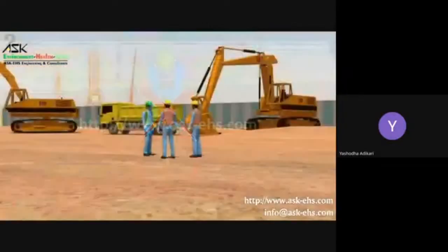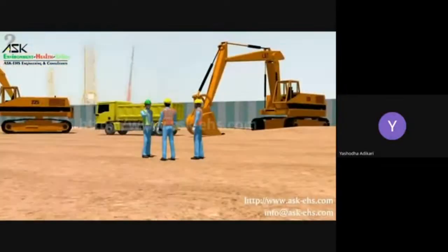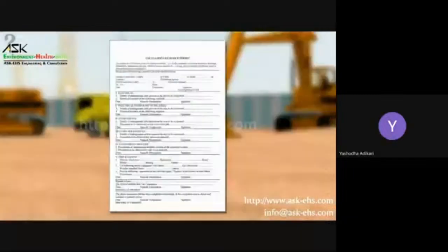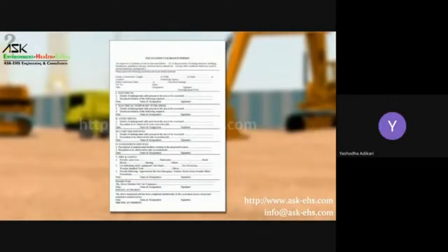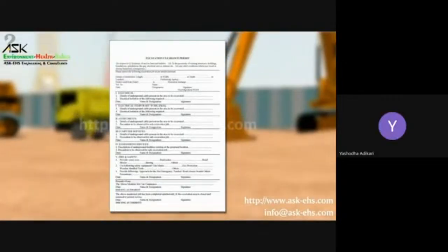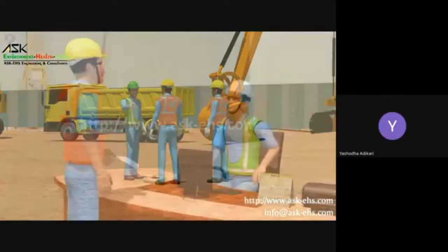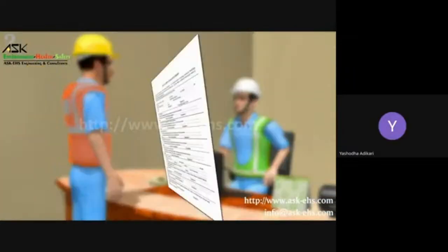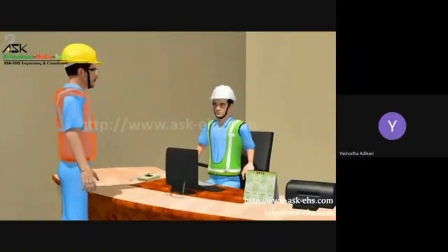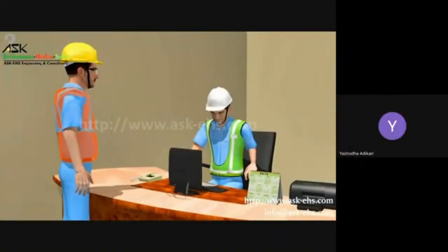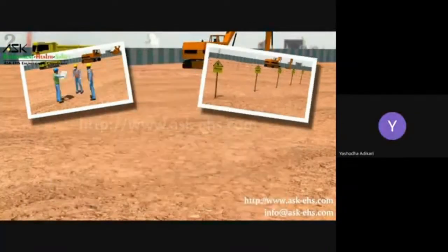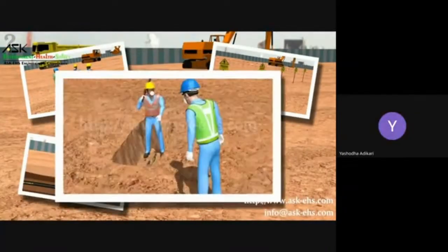Before starting any excavation, your supervisor will take a work permit for necessary areas that are to be excavated. This will ascertain the presence of underground utilities, and if they are present, then such utilities are properly isolated. This permit is given by the section in charge, and it is a clearance to start excavation and the corresponding safety precautions to be taken. Based on the work permit, your supervisor will instruct you to take one or more of the following precautions depending on site conditions.